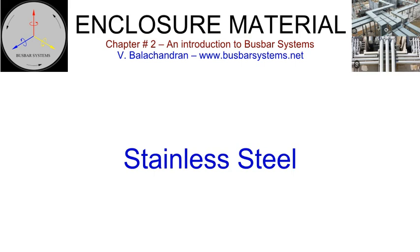Drug and pharmaceutical industries specify this material when the enclosed bus runs inside the plant. Stainless steel sheets and components are manufactured in two grades, Type SS304 and Type SS316. Both are austenitic steel and have very low magnetic susceptibility. Grade SS304 exhibits more magnetic property than grade SS316. As a crude approximation, both of these can be called non-magnetic and hence do not generate hysteresis losses in presence of the magnetic field generated by alternating currents.